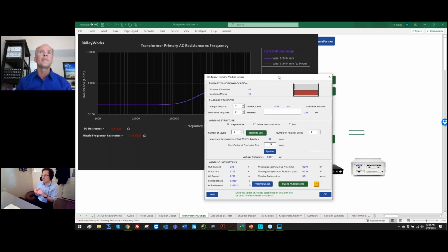When I'm winding a magnetic, it's not about the esoteric analysis. It's like, which winding has the higher turns count? That one goes on first, because you can keep that neat and flat. If you've got great big bulky wires or foil, once you put them on there and then you wind the fine wire after it, it doesn't work out so well. But here you go.